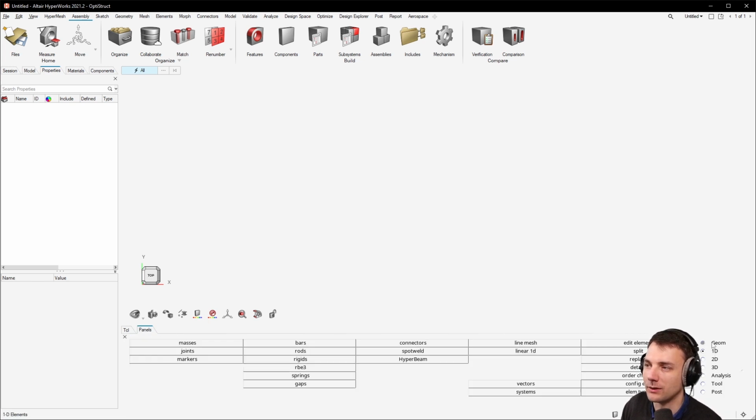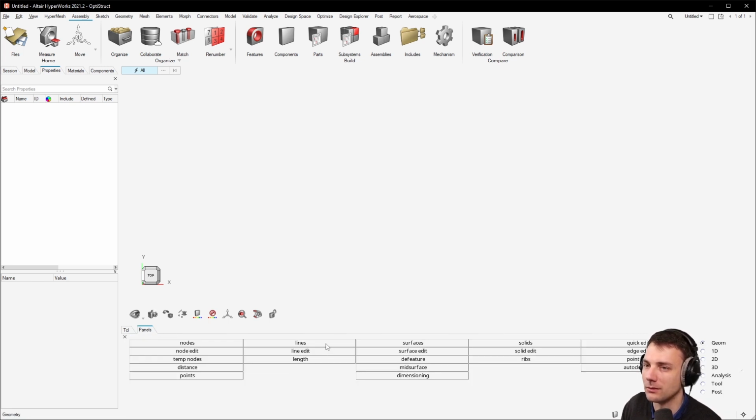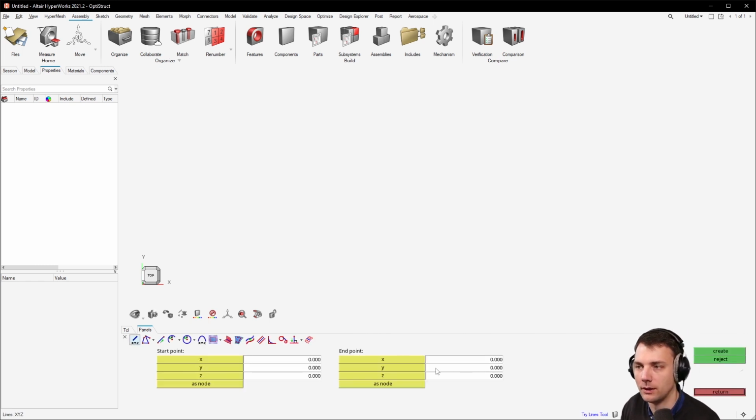We wanted to do this with geom lines. Yeah, I want to have that with a line because you could do this with two nodes and one element, but I wanted to have multiple elements, and that's why I chose to have a line mesh. I think that's easier. So lines, and then we have here 1000.